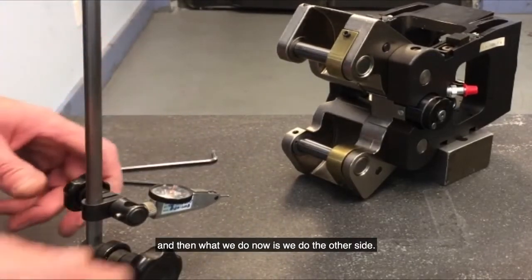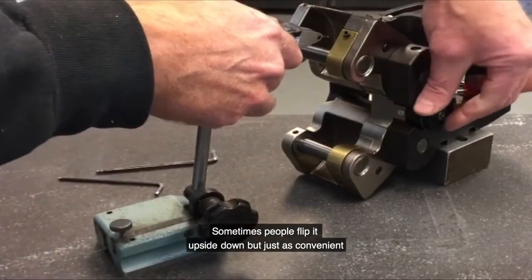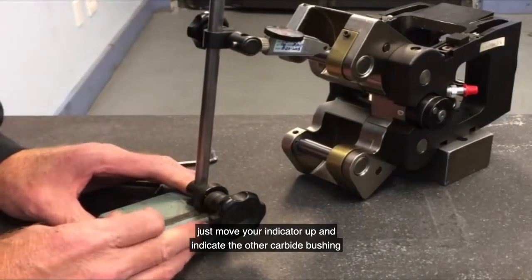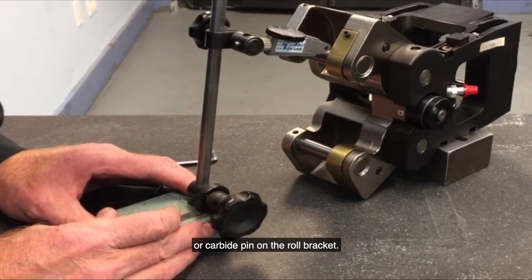And then what we do now is we do the other side. Sometimes people flip it upside down, but it's just as convenient because of the nice setup here to move your indicator up and indicate the other carbide bushing or carbide pin on the roll bracket.